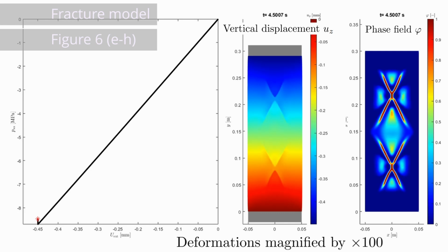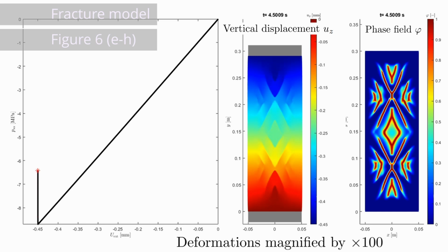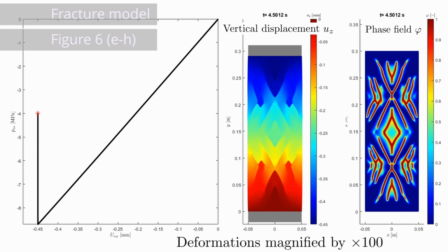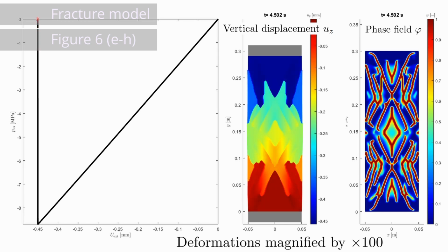fracture release energy. As a result, denser crack patterns are needed to dissipate comparable amounts of elastic energy, as shown here. While the crack pattern is more detailed, the overall mode of failure is still the same as when a coarser length scale was used, cracks forming in the center, branching sideways, and linking with parallel cracks to lead to